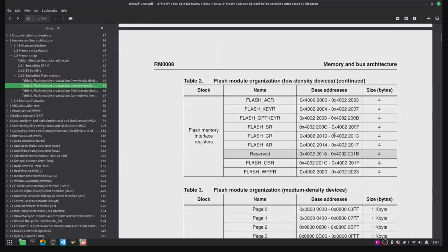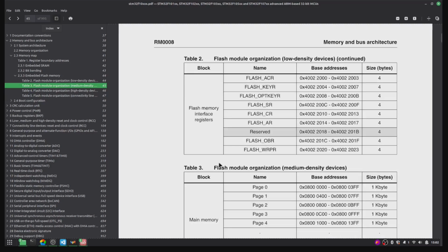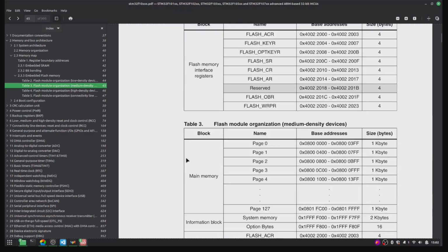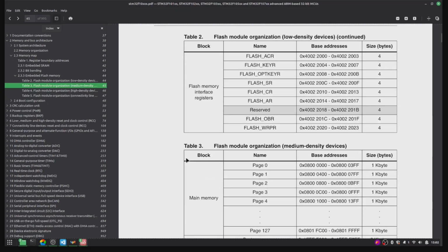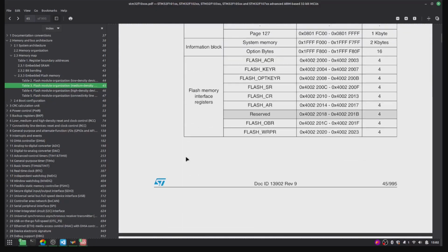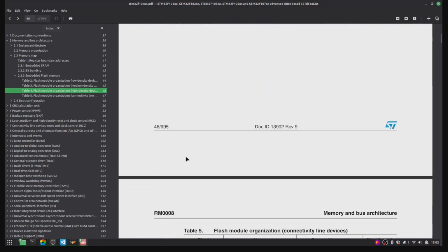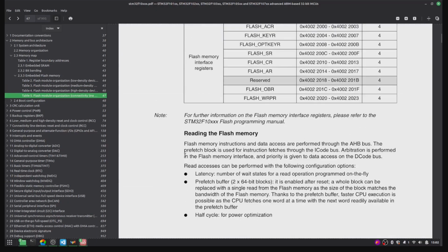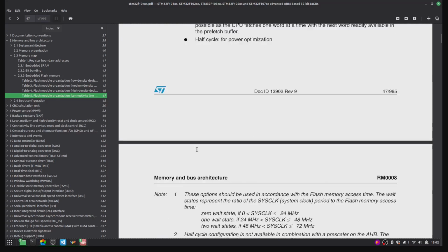There are certain registers involved when you are reading and writing into the flash, from the HAL itself. Usually either the JTAG interface or the internal boot ROM has access to these, but we can unlock the flash, write something into it, and lock the flash again. So the idea of flash loading is the ability to write into these pages.